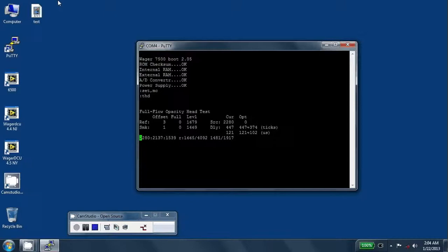Okay, that's good. And let's go ahead and flip it over to the other side and do the receiver. This is the side that is not emitting the green light, and this also has a potentiometer, and we will go clockwise on it, bringing the 1500 value up to 2100. Okay, now that we have the optics digitally adjusted, let's go ahead and hit escape, and that'll stop the numbers from jumping. At this point we'll type in the command calibrate, C-A-L, for calibrate, and hit enter.